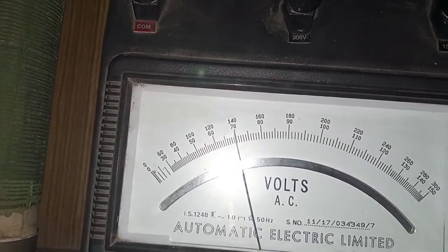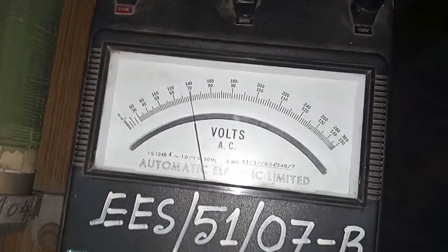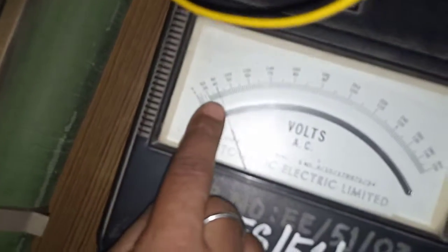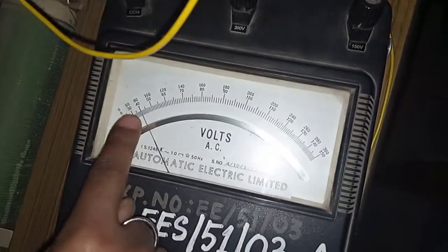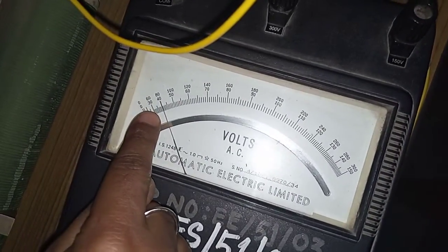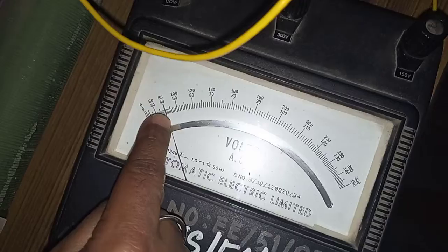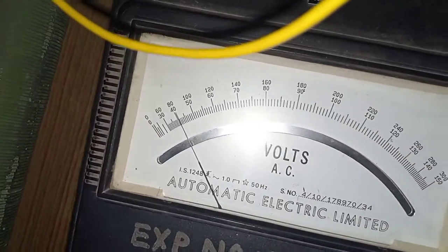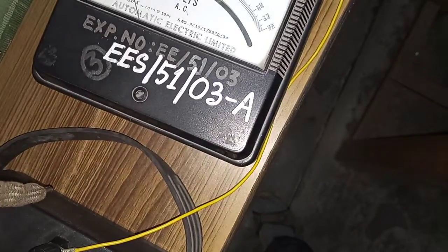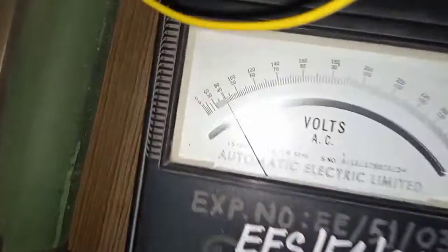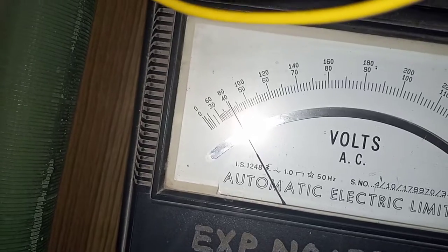So it is 140. So input voltage, this is measuring the line voltage, is 140 volt. What is our phase voltage? This is the phase voltage measuring voltmeter. How much is this? We have connected it to 300 volt range. So upper scale we will follow. It is 80. It is after that 82, 84, almost 85. So 85 volt is the corresponding, or 84 volt is the corresponding voltmeter reading. Not 84, rather we can say 83 volt is the corresponding voltmeter reading.